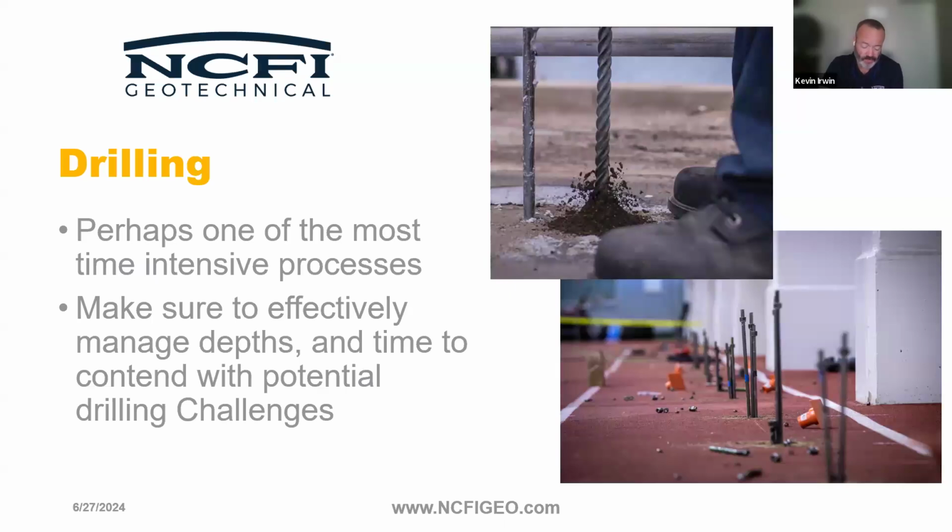One of the most labor-intensive things you'll have to do is the drilling for deep soil injection, drilling and driving, I should say, because we drill a hole typically, but we're not going to drill for the full depth of the injection tube. We're going to drive it the rest of the way.